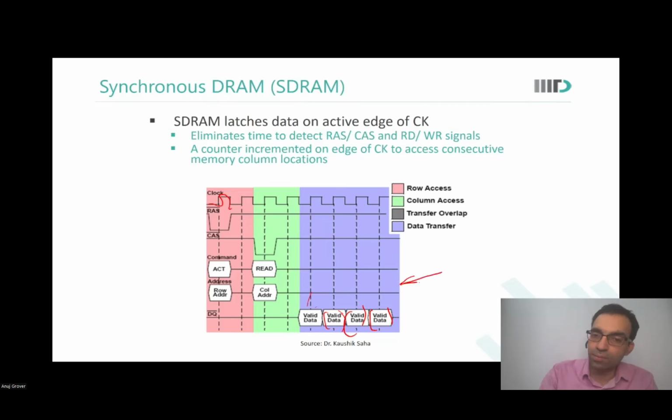Hello? So here we are fetching the data from a row only, like we give a row address. Oh yes. Look at this, the row address was given only once and the column address was also given only once, after that it was incremented internally, saying that the column address will change only one by one. Yes sir, yes. Okay.